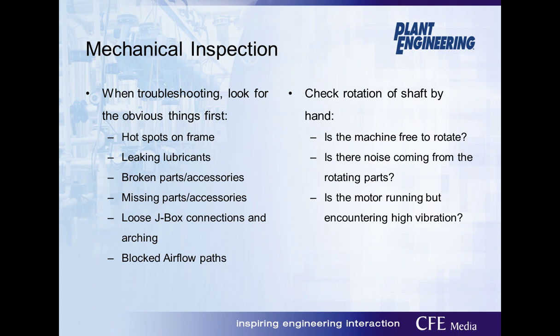We would look for leaking lubricants under and around the motor. Leaking lubricants can play a big role in understanding if the motor bearing grease is getting too hot or if the motor bearings are not getting enough lubricant due to the leak.